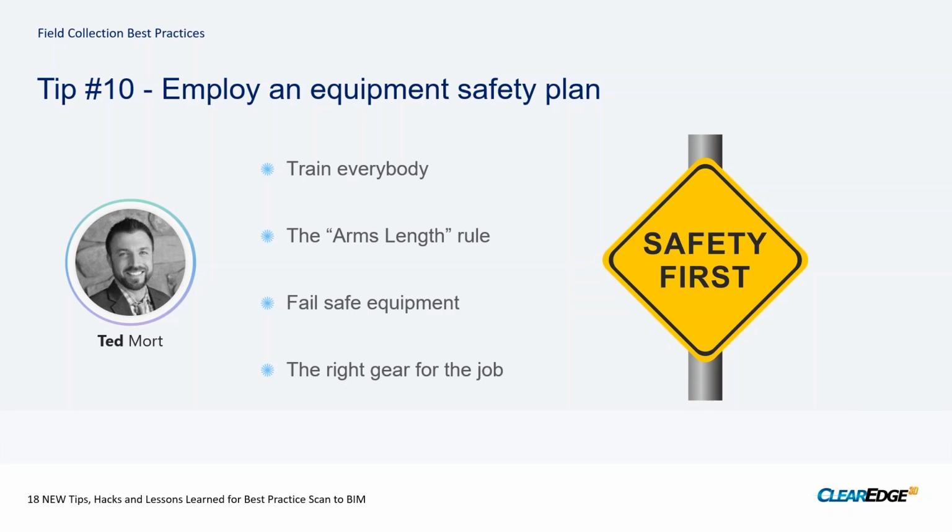There's a tendency right now to go out and use camera equipment to hold up scanners, and the reality of those carbon fiber legs is that they do like to give out when you put a couple pounds on them. Not used to that kind of weight. So you can find options out there that are spec'd for weights and uses that are greater than what yours is. Highly recommended. It's worth every dollar there to prevent that damage from occurring.